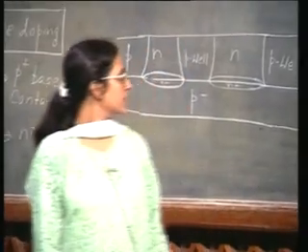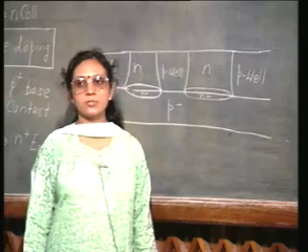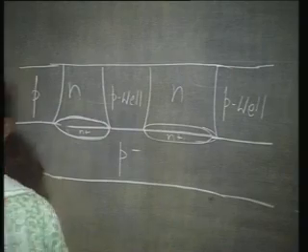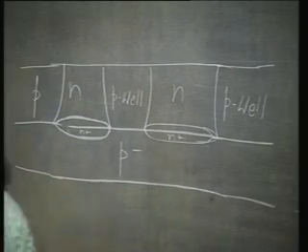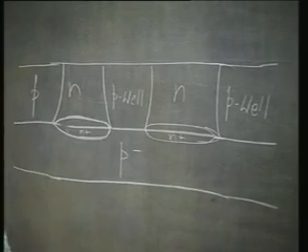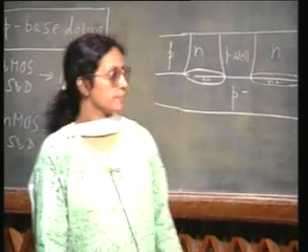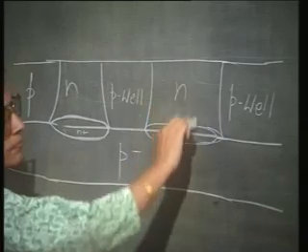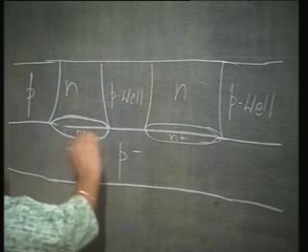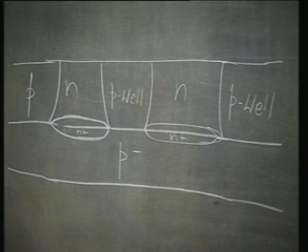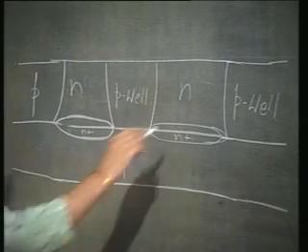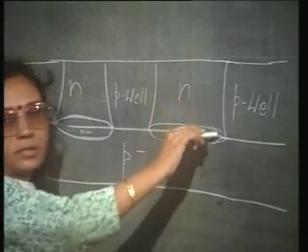So, the features of this particular process flow is this buried N plus layer, and you can also have a deep N plus collector here and here, that will also cut down the shunt resistance of your CMOS substrate as well as will reduce the collector resistance, right.